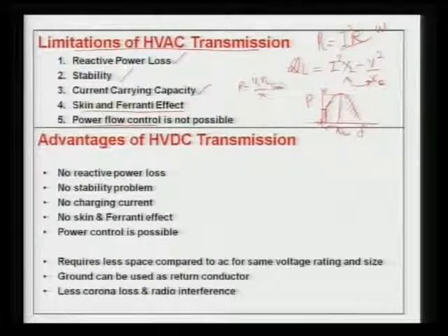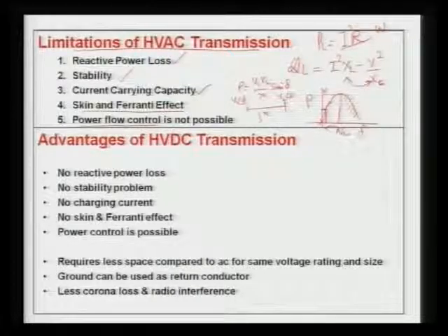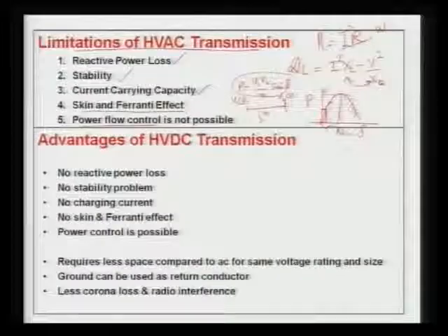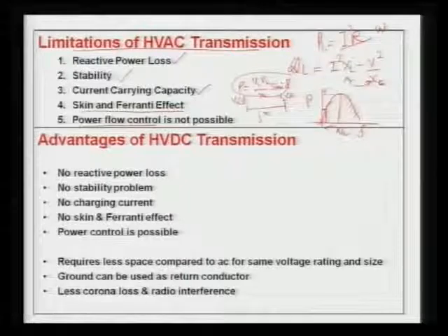This is basically the two elements, and this is your delta, if this is angle 0 here, I can say V2 here and V1, and this is the x of the line. So the power flow can be simplified. If we assume the line is lossless, we get this power flow, and we can go for the minimum delta. This stability concern again doesn't arise in the DC system because delta doesn't arise; we only talk about the voltage and the resistance. So no x, nothing. This concept doesn't arise in the DC system.